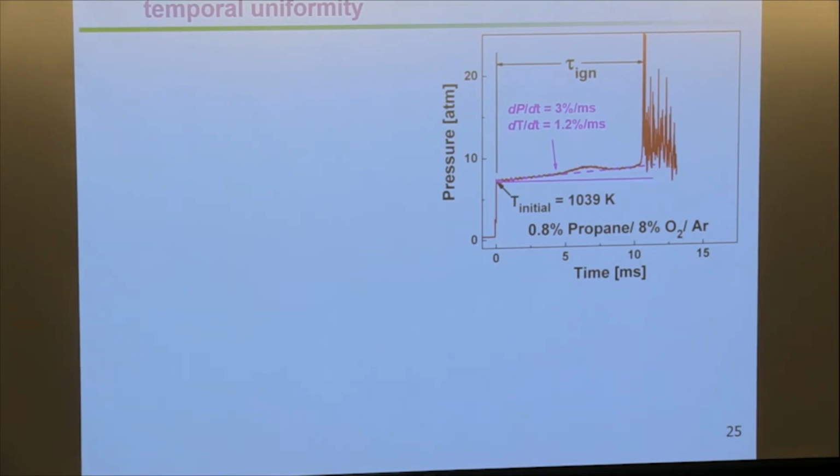And for the longest time, until maybe 10 or 15 years ago, people just ignored this problem and said, well, it's too small a problem to worry about. So they would calculate the ignition delay based upon the initial pressure, and they model it. They try to compare the model with the measurement. So here's the measured time right here, ignition delay. But it bothered me that the models didn't work well in a regime like this, 1,000 degrees.